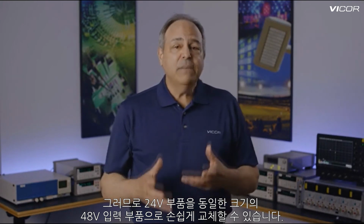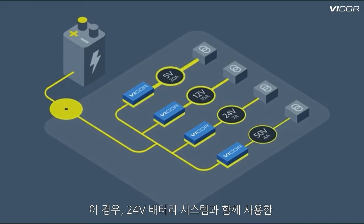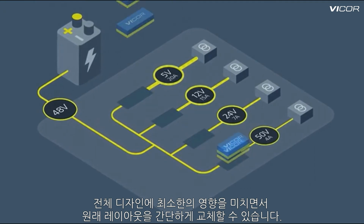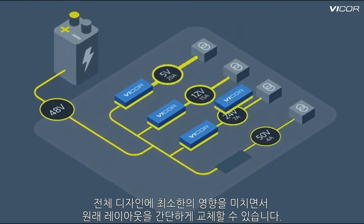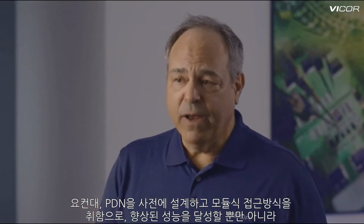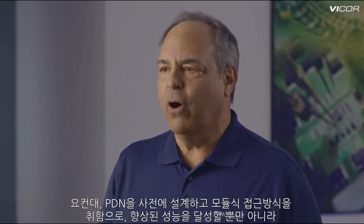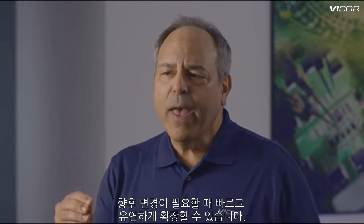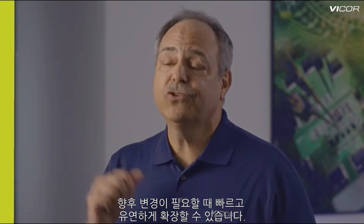Fortunately, DCMs come in a variety of input voltage ranges, such that 24-volt parts can be swapped with 48-volt input parts of the same size and power capability. In this case, it becomes a straightforward replacement to the original layout with minimal impact to the overall design used with the 24-volt battery system. Once again, designing your power delivery network up front and using a modular approach not only helps achieve greater performance, but it also allows for quick and flexible scaling for future changes.